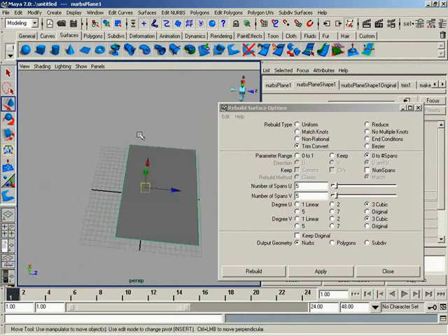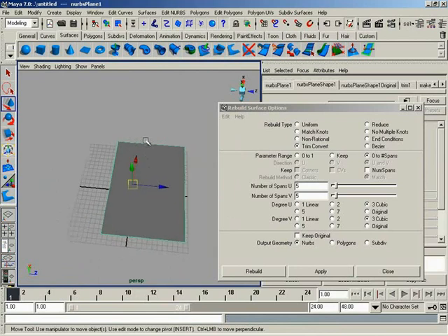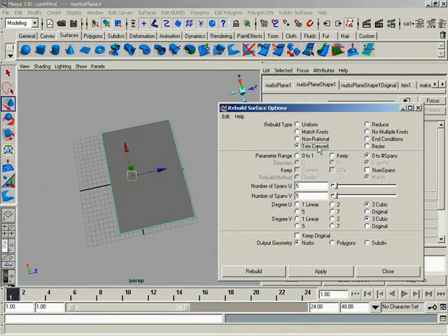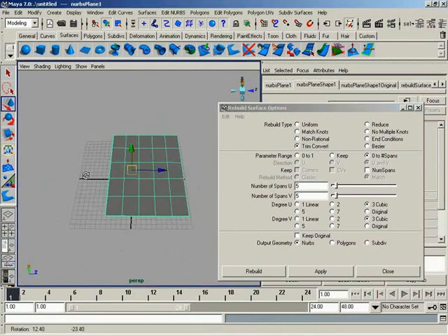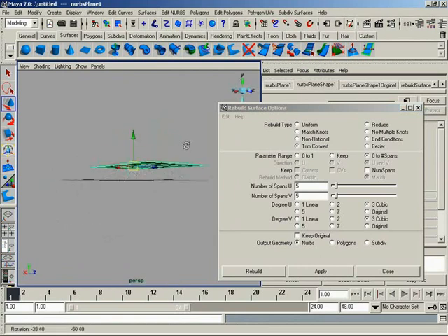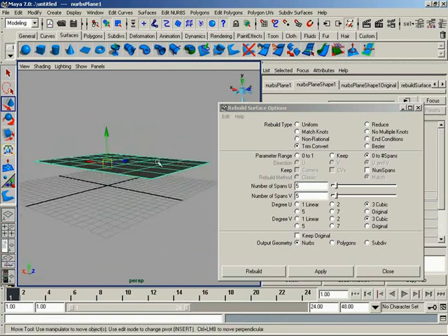So why can't this be its own NURBS panel? Well, we can come down here to Trim Convert under our Rebuild settings. We'll make this a 5x5 panel just for this example. Click Apply, and boom. Notice it becomes 5x5. If we right mouse on it, notice the trim edge is gone. This is now just a plain Jane common everyday NURBS surface.